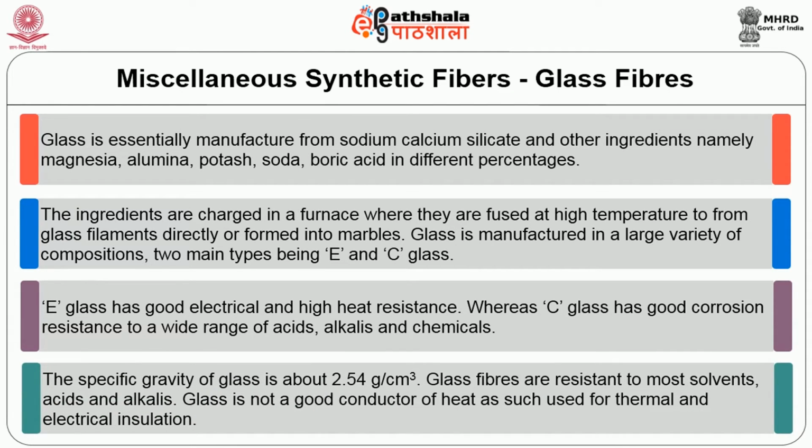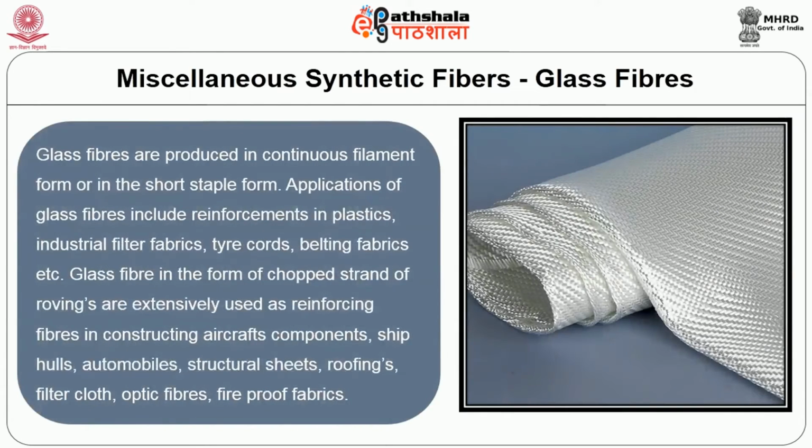The specific gravity of glass is about 2.54 grams per cubic centimeter. Glass fibers are resistant to most solvents, acids, alkalis. Glass is not a good conductor of heat, as such we use it for thermal and electrical insulation. Glass fibers are produced in continuous filament form or in the short staple fiber form. Applications of glass fibers include reinforcement in plastics, industrial filter fabrics, tire cords, belting fabrics, etc.